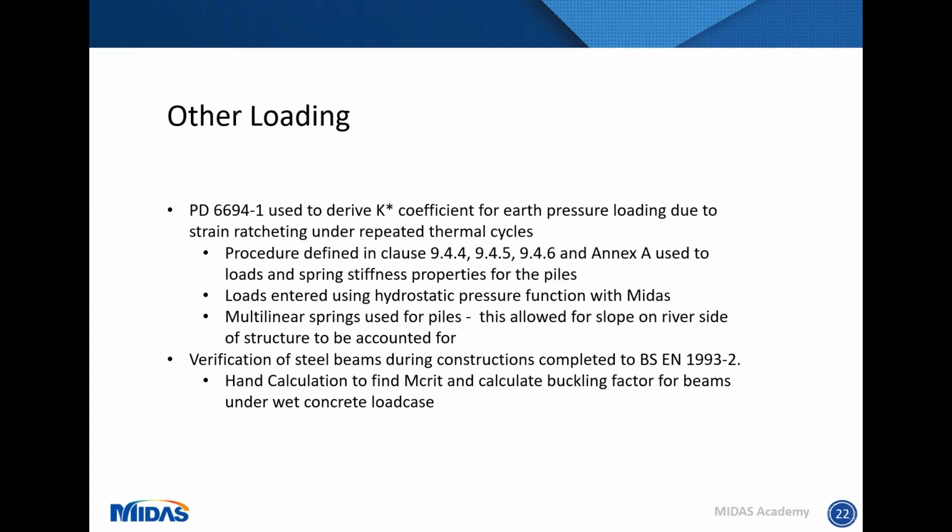Obviously, as this is an integral bridge, we have the effects of strain ratcheting at the abutments. For this model, and just for my level of experience at the time, I was not able to use, I think there's a function within Midas that is able to try and recreate some of the effects of strain ratcheting. We basically took the approach where we referred to PD6694 to find the K-star coefficient for earth pressure loading. So the procedure that we followed is what was defined in clauses 9.4.4, 9.4.5, and 9.4.6, as well as Annex A of PD6694.